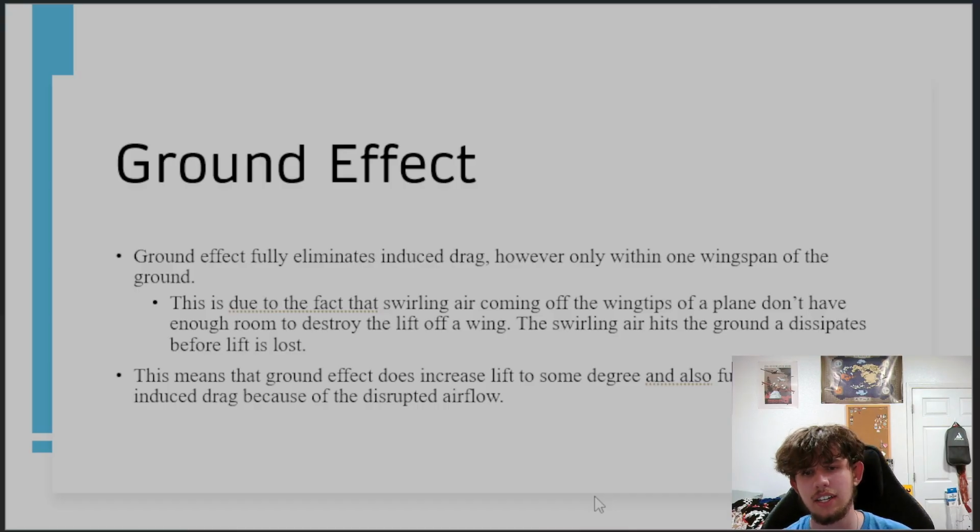allowing a safer landing. It's also the reason why on most of the landings, right before you go to touchdown, the plane seems to fly a bit smoother and may also balloon. You're getting within that ground effect. Wingtip vortices and induced drag no longer have that major effect on your plane that they did just a moment before. But those are the major forces of flight.